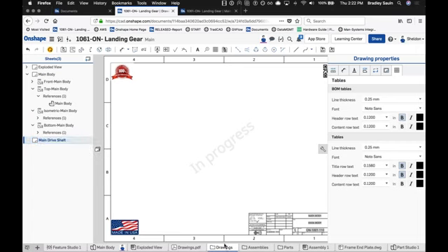And the same thing for the drawings tabs at the bottom. So as I have a tab selected, I can come over here, make a selection view, and I'm good to go for just that quick, instead of having to right click and select rename. That Shift N option will bring up those details so you can start typing and not have to use your mouse as much, just for some productivity increases.